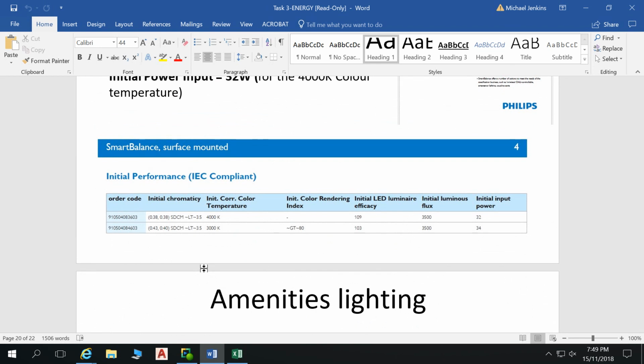Yeah, 250 square meter, and then work out 750 by 1500, just a little square, and then just line up everywhere. Then 600 mil gap. Yes, 600 mil gap. How many can I put into the roof? Yes. So how many panels can you fit on the roof?